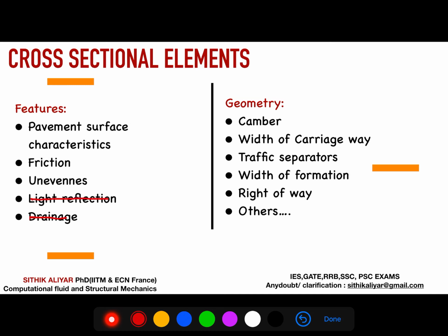And the light reflection, I hope you know the light reflection, it should be less reflectable during morning and also during the night. That's why they have preferred a bitumen color. If it is a black color, I hope it will be less reflective, and if you remember, the concrete road will have more reflection. That's why on national highways and state highways we provide bitumen, and even on national highways they have provided such a color that the light reflection is already very low, so the road will not create any problem, but the people coming from the opposite side is nowadays creating a problem. So the pavement surface should be less reflectable, and it should have very good drainage properties, like it should not absorb the water, it should drain off the rainwater quickly.